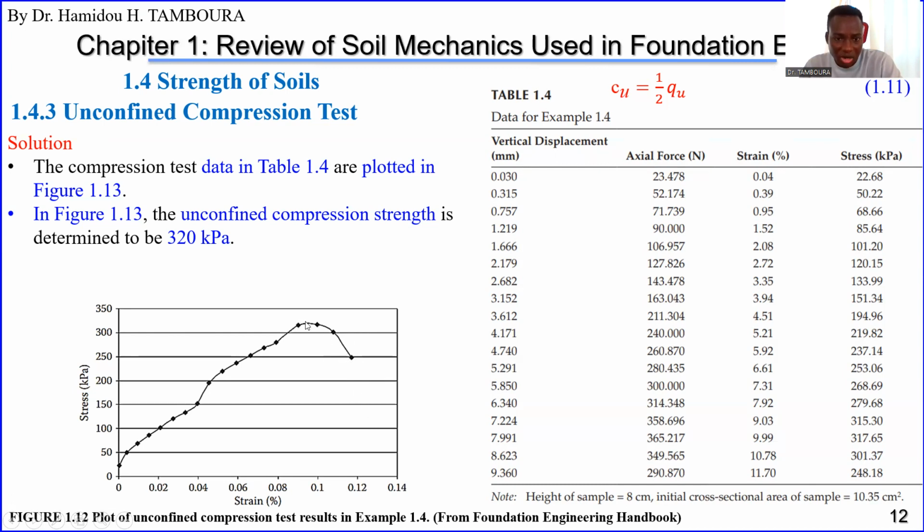So the maximum here should be taken as the strength, 320 kPa. This is the maximum stress that the sample can support. Above that, it will decrease, and you will have larger displacement for a small increase of the stress.